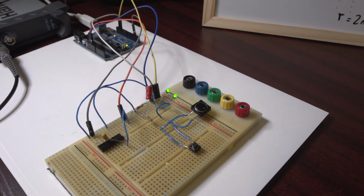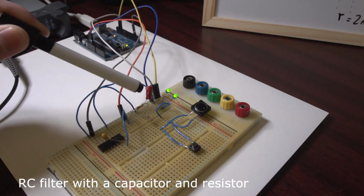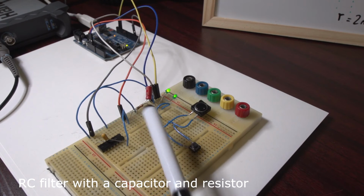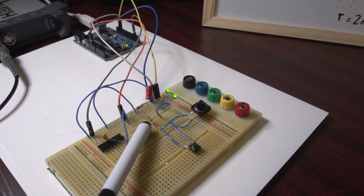Here's our little RC filter circuit. We've got a 2.2 microfarad capacitor, that red capacitor there, going down to ground across the switch basically. We've got our 10k pull-up here, 10k pull-up there to 5 volts. We've got the 220 ohm resistor, which is in series with the buttons.